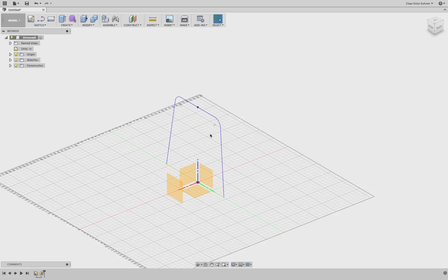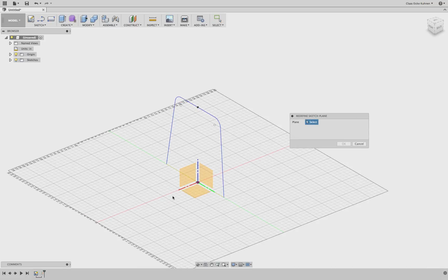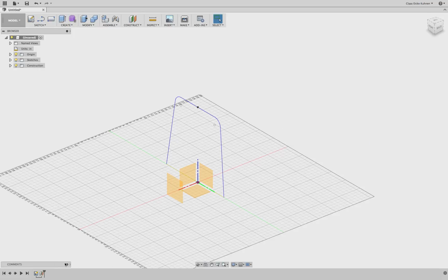and then bring this over 9 inches. Okay. And we know when we go to the sketch, select it, right mouse button click, with redefine sketch plane now, we can actually say, well, take this sketch, but instead of putting it onto the center construction plane, put it onto this new construction plane. So then you click OK, and then this construction plane we created is not there. And that is because we created it afterwards.